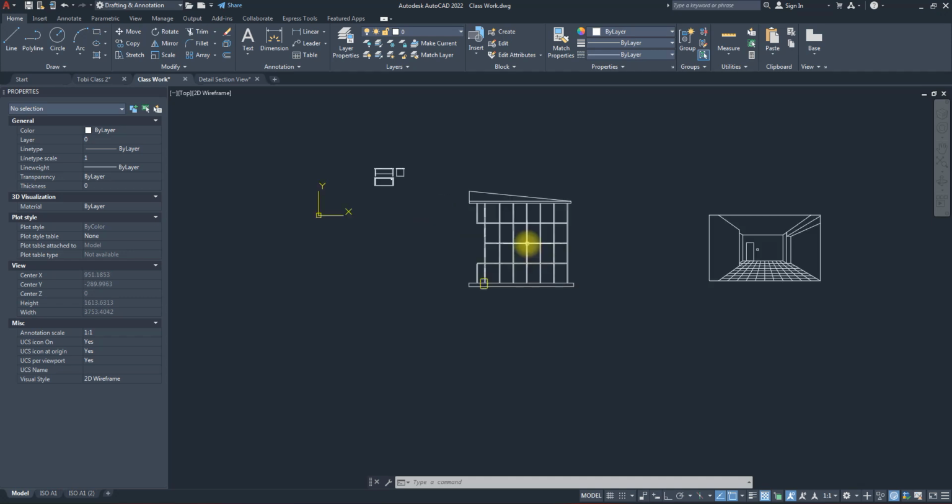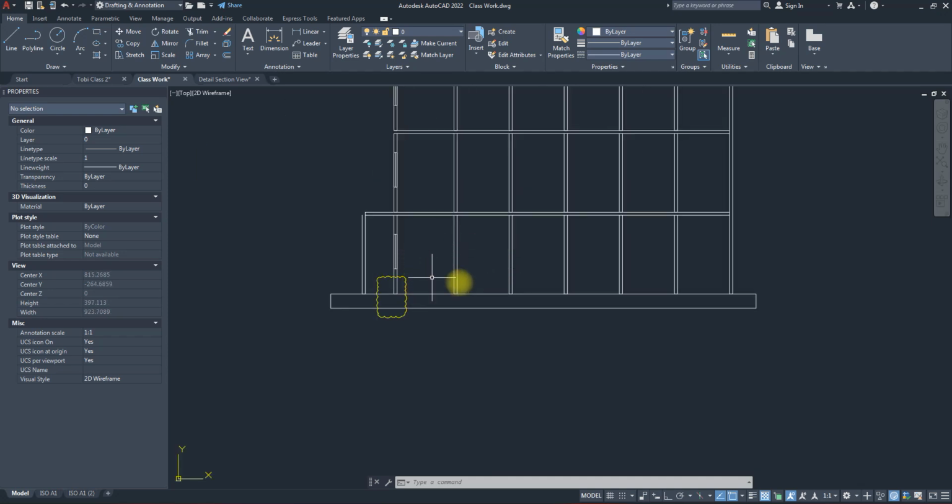What happens is that if I create different hyperlinks or OLE objects, bringing them here, or even use my blocks, say in the case of this drawing I want to put doors here. If I use the block approach that we've done, assume we've created a block of our door and I want to bring it in. The thing with using blocks, or any of these links, is that the more of these components you add, the larger the file size of this drawing becomes. And that's when AutoCAD starts slowing down and lagging, which eventually crashes.